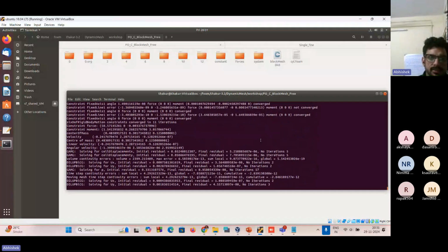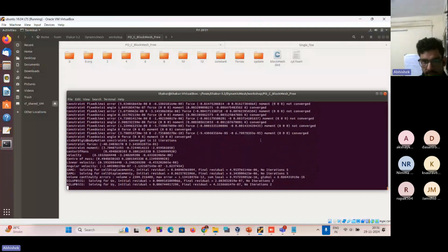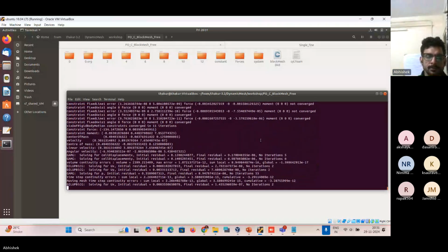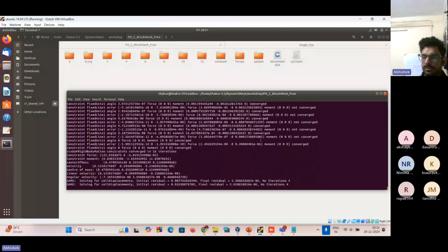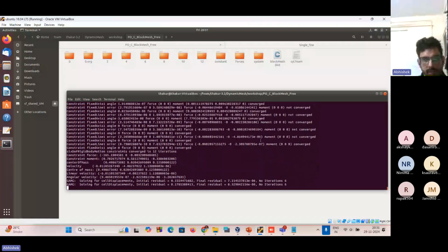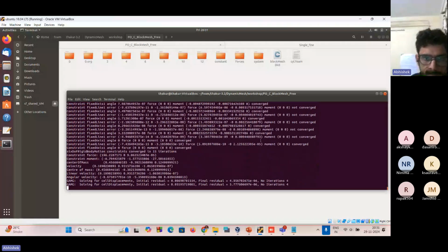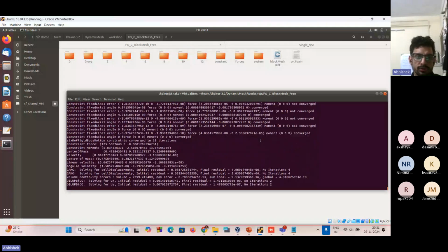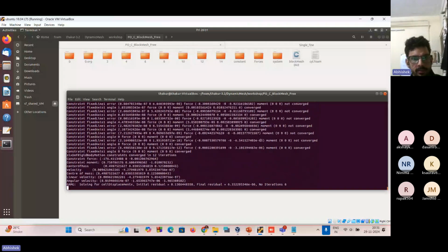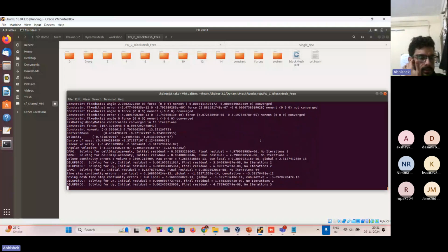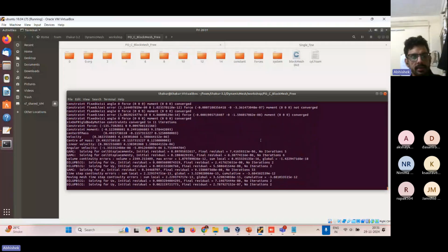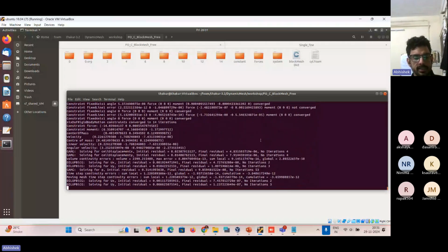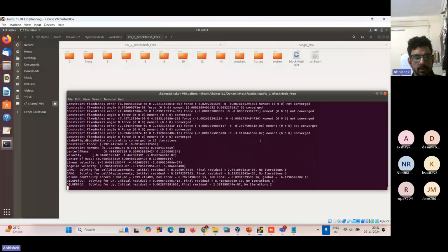Sometimes what happens is that with this 6 degree of freedom rigid body motion library, achieving convergence is very hard. For cases where the forces can be large, for example in initial transient simulation, forces can be very large. In those cases, sometimes the 6 degree of freedom library is not able to come to a converged solution, converged updated displacement and velocity of the cylinder.